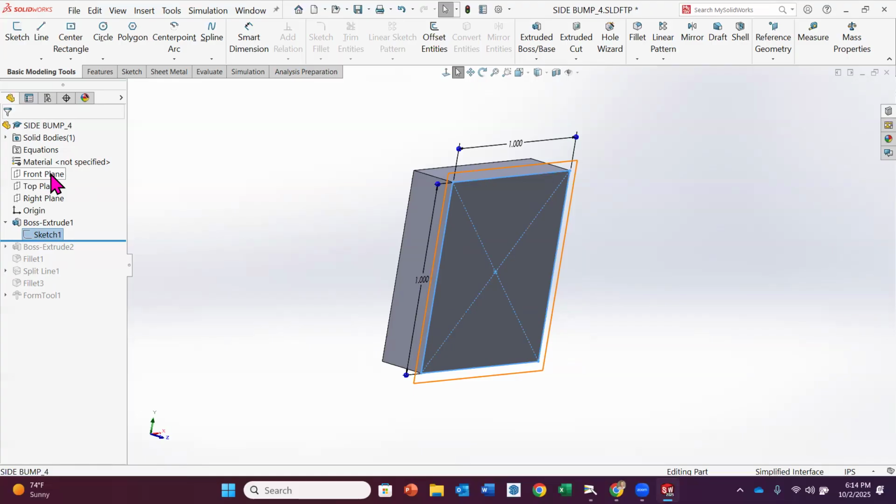Now, typically when you extrude this, it's just a rectangle, and I'm going to extrude it to get my depth here, okay? When you extrude it, you have to flip the direction because you want to extrude back from that surface, okay? Because that's going to be your top surface, and that's going to be the surface that we are going to be putting our actual form on, okay?